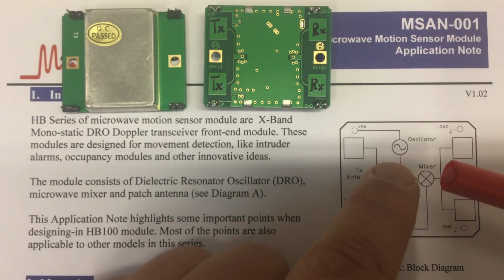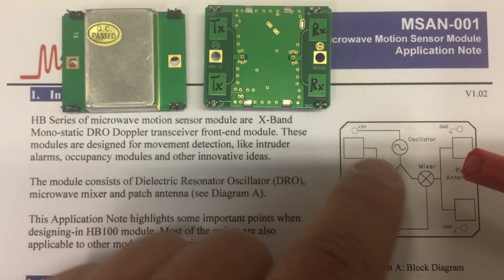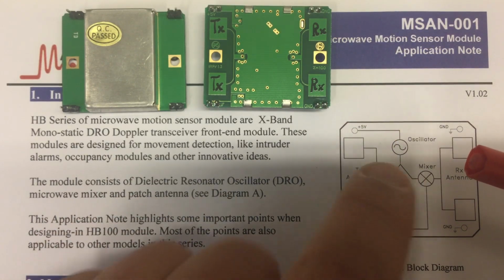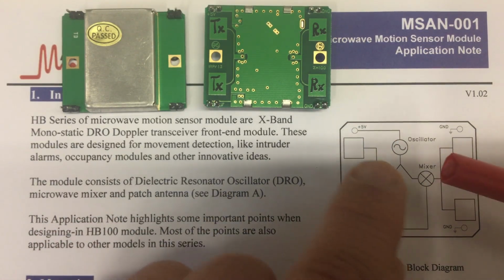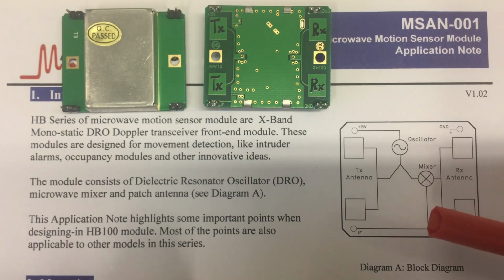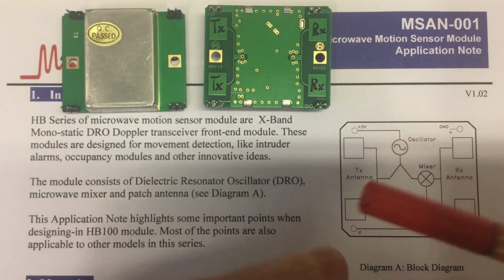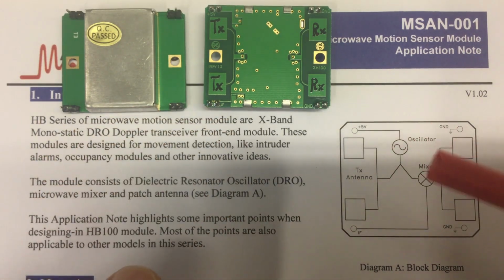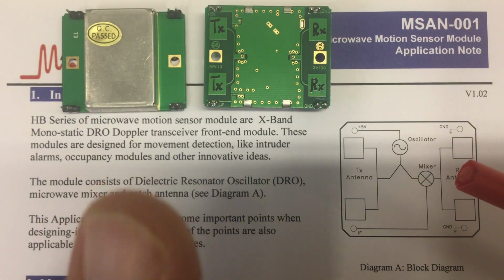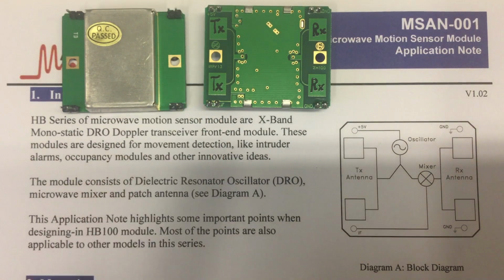And both go into a mixer. The oscillator output is, of course, attenuated properly. And the output from that frequency mixer goes to your intermediate frequency output. That's all. By the way, the mixer also consists of just one transistor.